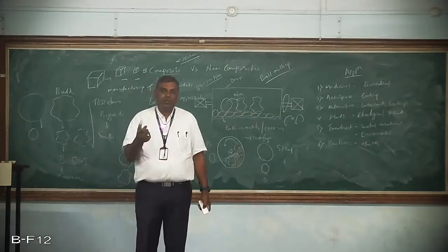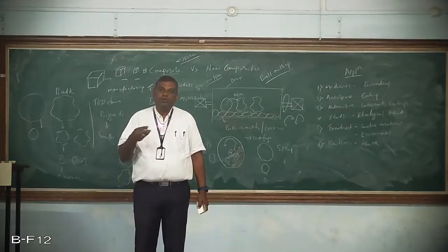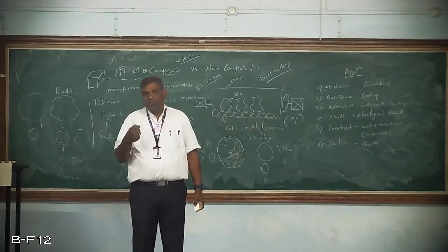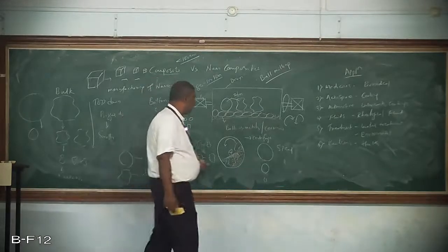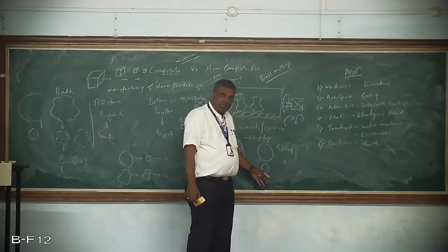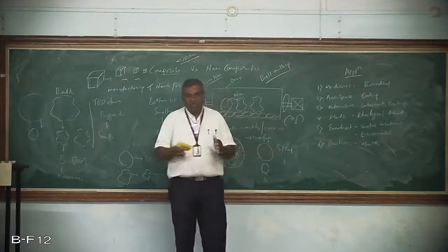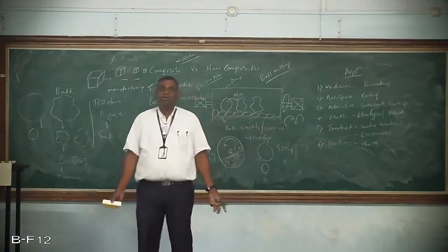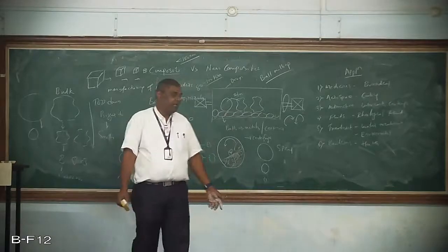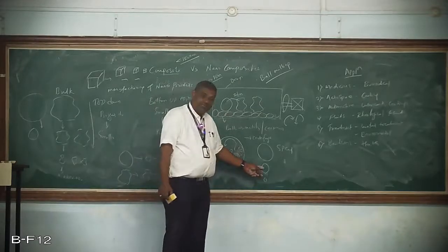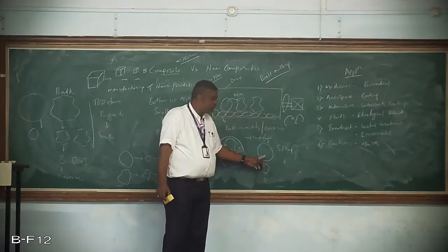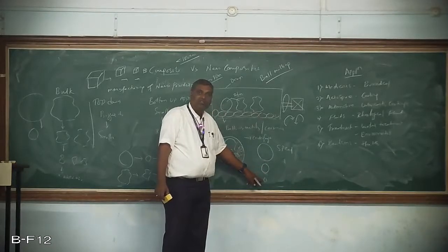If I take the smaller balls and allow them to rotate for 1 hour, 2 hours, 10 hours, then the amount removed from the bulk material is very less, but it is of uniform size. In the same 1 hour, if I use the bigger balls, I will get the bulk material, but there is no uniformity in the particle sizes. Then we can have a combination of both. This will give better results compared to the bigger size as well as the smaller size.